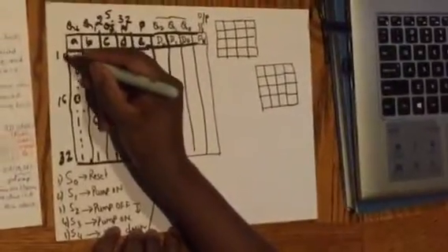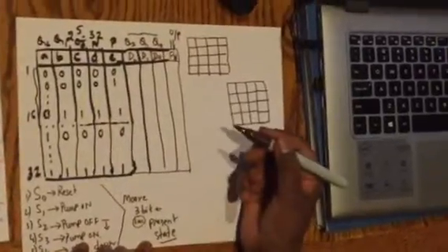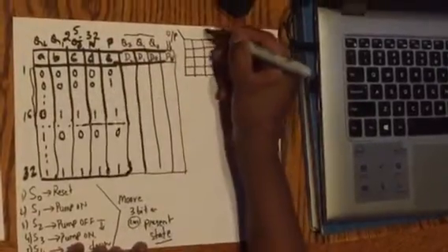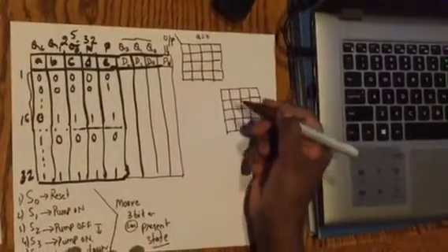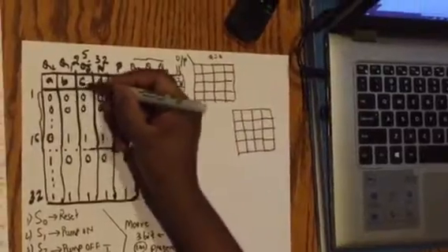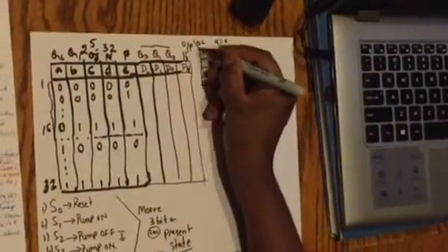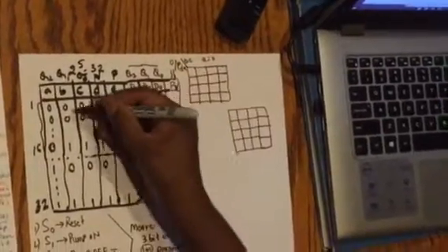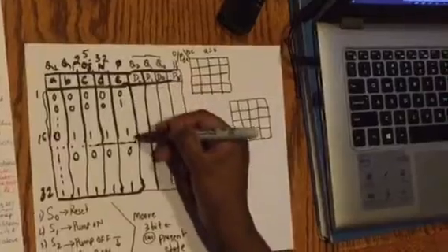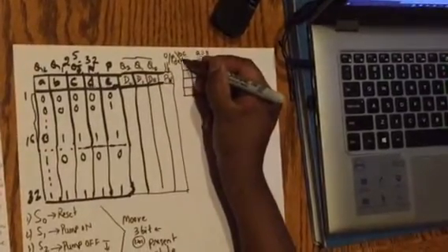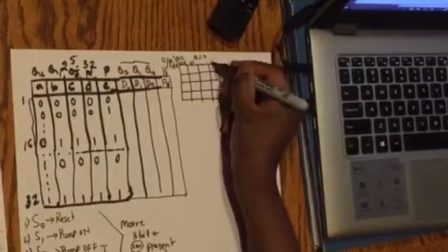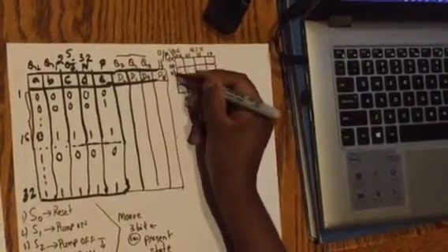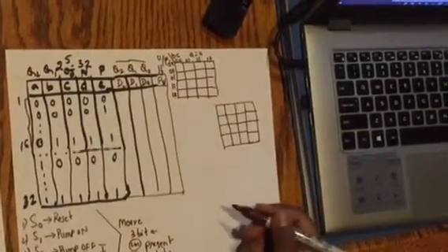For the first 16 in this table, A is 0, so we take those numbers and put them here. B, C, D, and E are the 4 variables for the first map. So this just runs as a 4-variable K-map combination, where this is 0, 0, 0, 1, 1, 0, 1, 1, and on the vertical side, 0, 0, 0, 1, 1, 0, 1, 1.